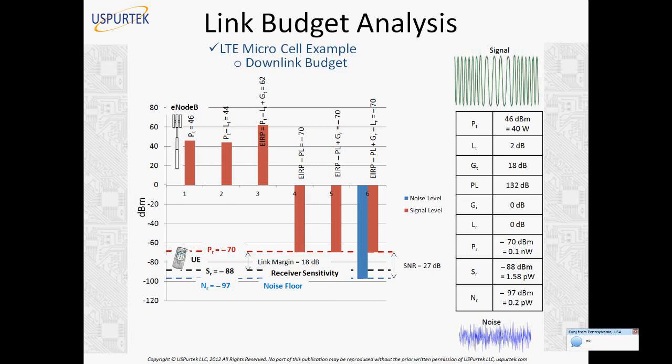This houses the BTS as well as the BSC, the base station transceiver system as well as the base station controller. Both are in the same box. So instead of having multiple boxes, in one box we have both functionalities. In an LTE cell tower deployment, you just need an antenna and an eNode B. The eNode B is a box which houses the functionality of BTS as well as BSC, and then you have an antenna up in the building somewhere, connected by optical fiber cable. The antenna amplifiers are located near the antenna. eNode B is an industry standard terminology used by 3GPP to describe that box.